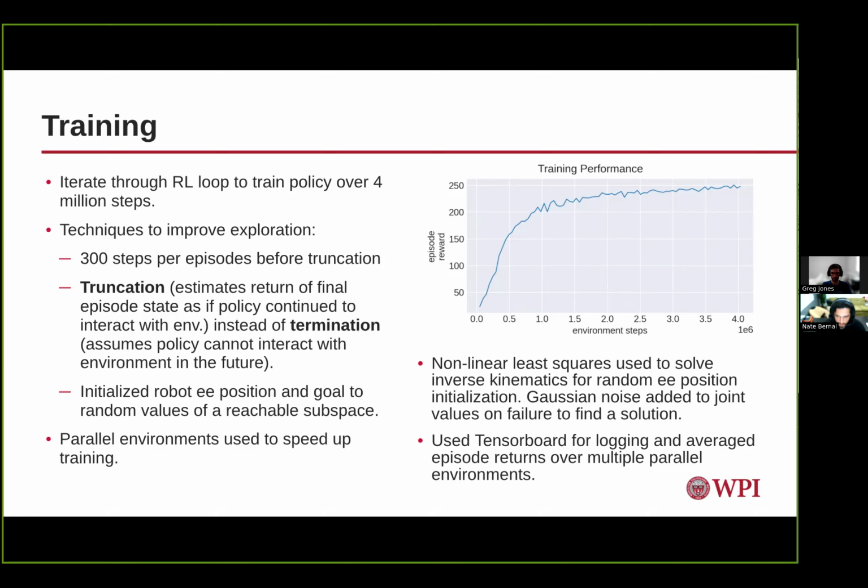So our evaluation results show that the PPO policy handled moderate changes to the arm's mass and inertia very well. For scale factors up to 2.3, total episode reward stayed essentially flat, indicating little to no performance loss.